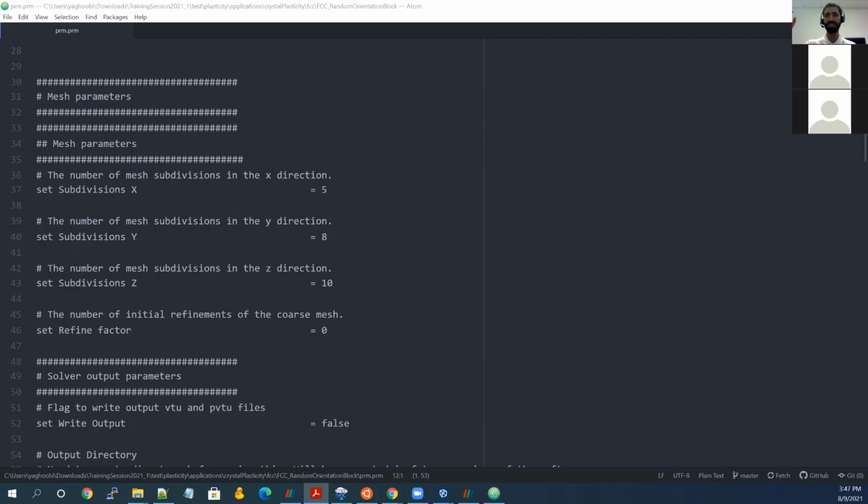If you read in an external mesh from another mesh generator and not generated by deal.II itself, then you might have round-off error on your boundaries. For example, when deal.II generates the mesh, it's precise. So you have from 0 to 1, and if you define the node on one face to get loaded, then there is no round-off error. So you don't need to have any limit for the uncertainty for applying that boundary condition.